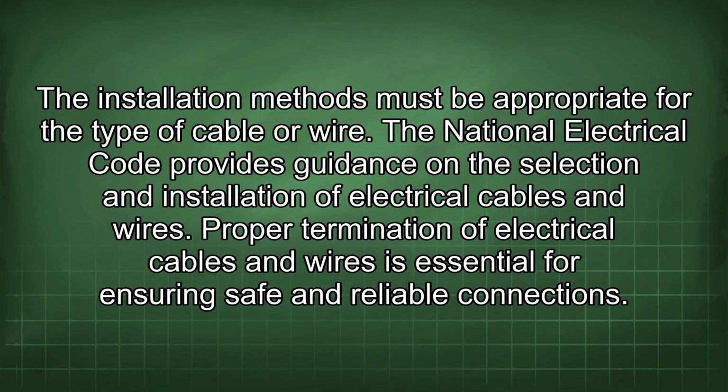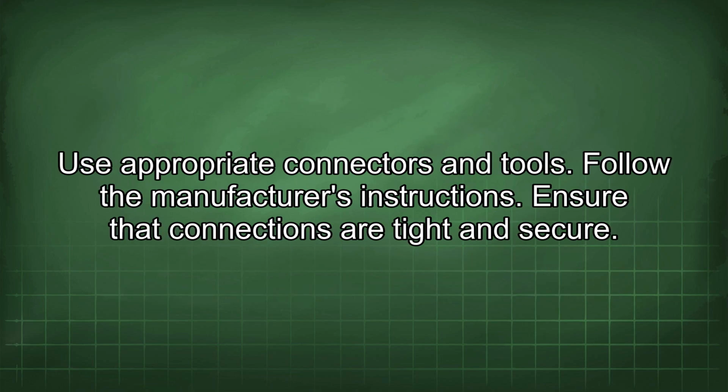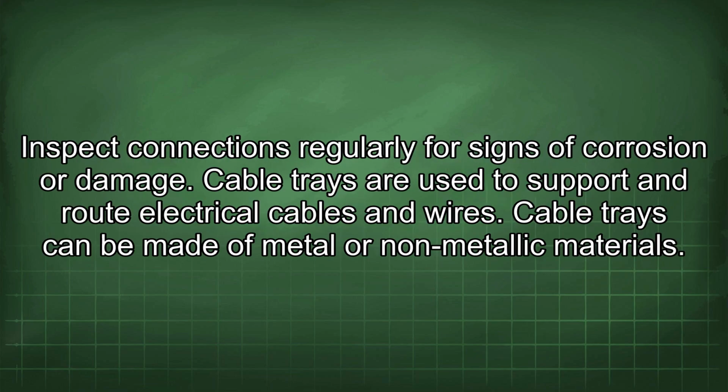Proper termination of electrical cables and wires is essential for ensuring safe and reliable connections. Use appropriate connectors and tools. Follow the manufacturer's instructions. Ensure that connections are tight and secure. Inspect connections regularly for signs of corrosion or damage.